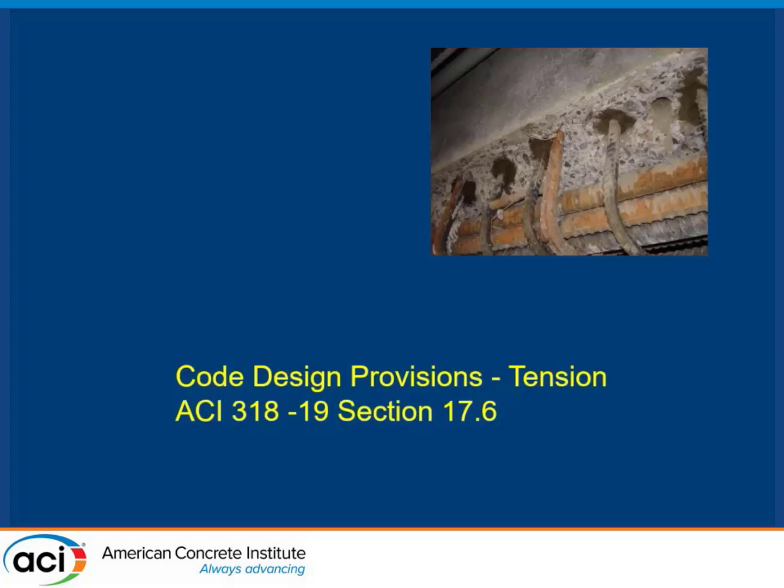Yes? So some of the material I read about the different kind of question said that the program managers and the construction managers were pushing for adhesive anchors, and the design engineers were pushing for the original design of expansion anchors. It seems to me that adhesive anchors require a little more inspection, have to be designed with fewer, and you're slower. So that seems backwards to me. Do you know anything about that?